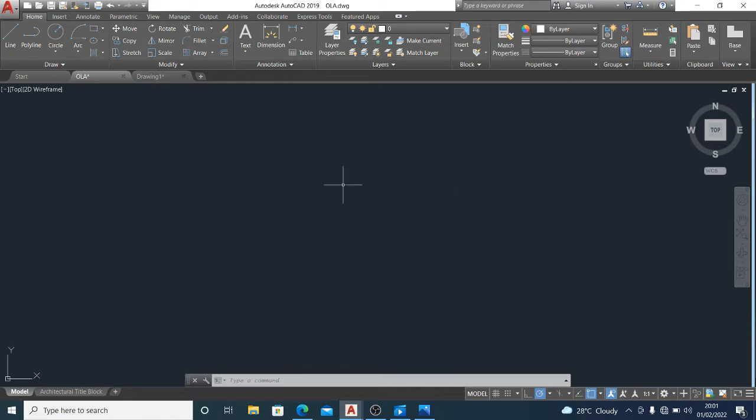The first that I will be showing us is ortho and polar. There is something we call ortho and polar. I showed us how to draw lines in our last tutorial. Once you click your line tool and you come here, you have activated the line function. Then my line can be drawn straight. You can see that there is a particular track my line is following, and this track is because my polar tracking is on. It's because my polar tracking function is on.